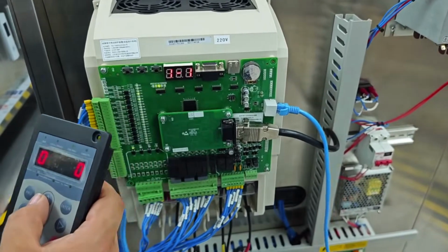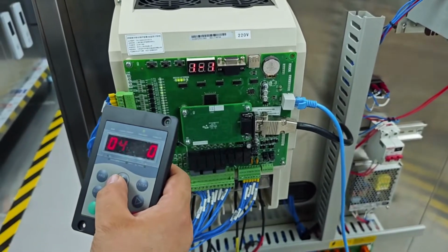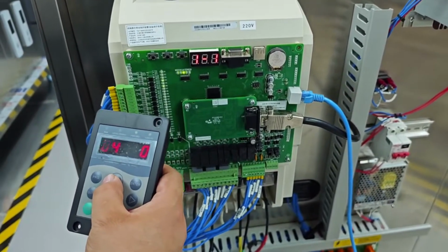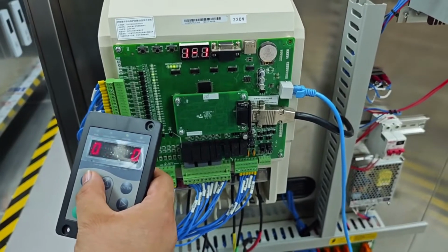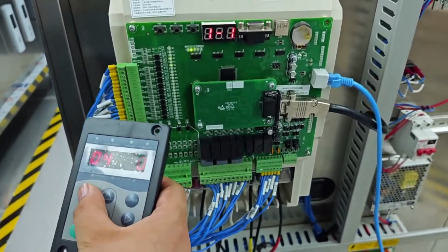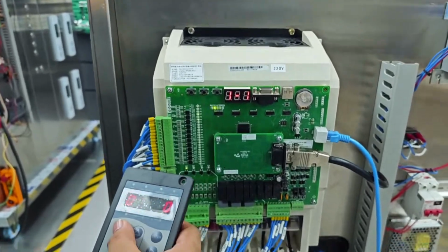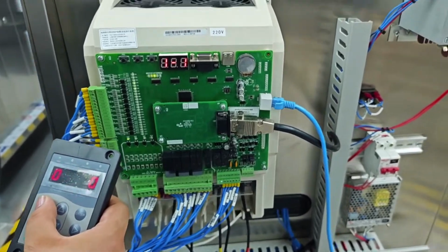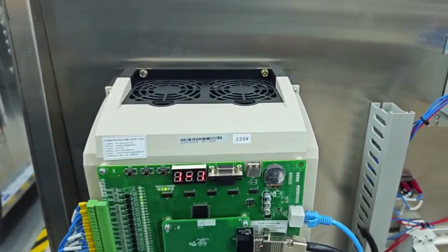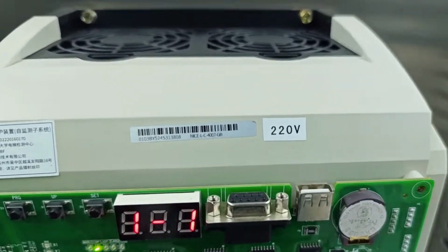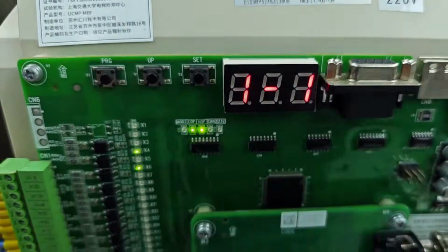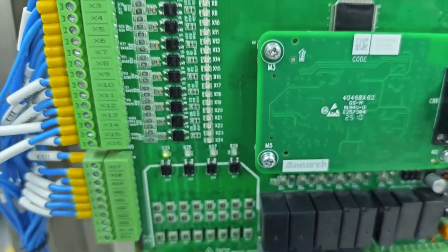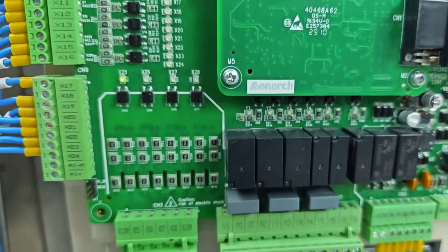Bit 14 equals 0 disables safety door lock detection. FE32 bit 15 equals 0 disables door lock short circuit detection. F641 bit 12 equals 1 enables door delay before reopening. F538 equals 0, F539 equals 0, and F540 equals 0 disable door lock high voltage detection.